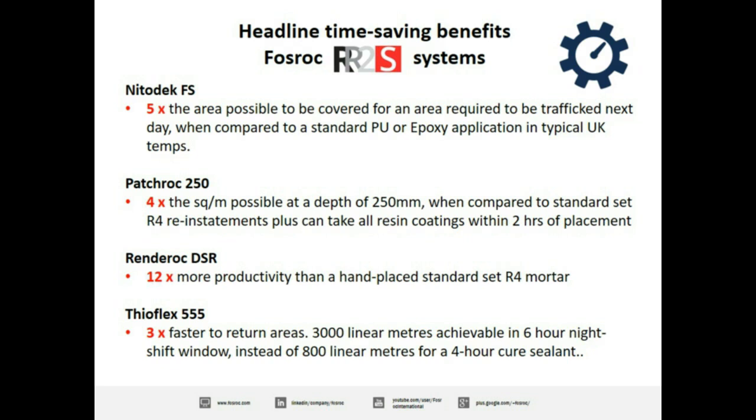So we've moved through Nitec FS, Patchrock 250, the Renderock DSR, and the Fireflex 555. And let's just sense check some of the key points of that. So 5 times the area possible to be covered, and trafficked the very next day when you compare that to a standard PU or epoxy, certainly in typical UK temperatures. We've looked at 4 times the square meterage possible with the Patchrock 250 compared to a standard micro or hand-applied concrete reinstatement. And again, it can take just 2 hours to have a resin coating, a highways approved waterproof system